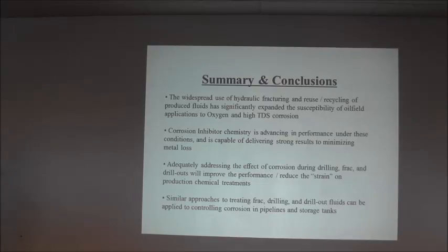There's still some advances, I believe, that need to be made, but there are some interesting improvements, and some companies, some manufacturers that are working on chemistries to make better corrosion inhibitors for these conditions, for high oxygen, high salinity brines, calcium compatible, high temperature compatible, etc. So there's still some way to go, but I think right now some very good results are being achieved. It's just a different way of thinking, away from the traditional amine and quad type chemistry to more polymer and phosphonate type chemistry.